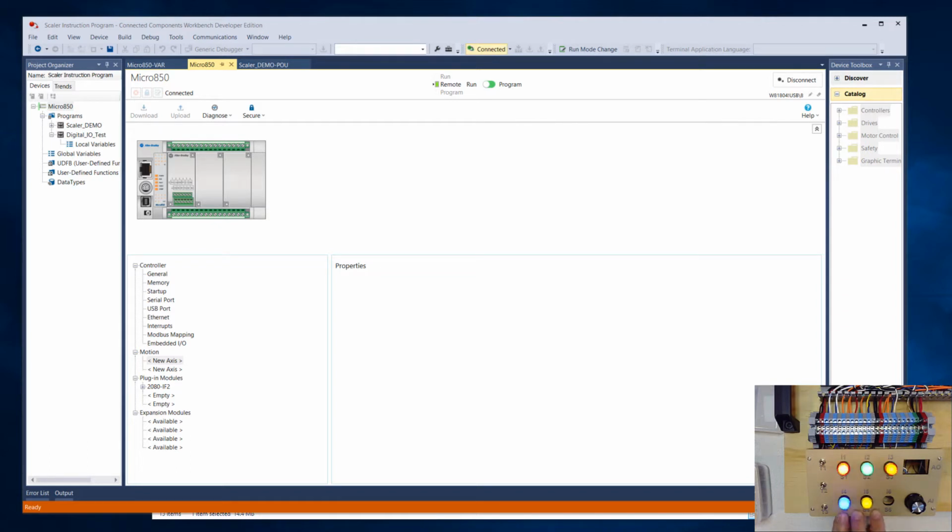So you can see it's flashing all of my lamps based on T3. Same thing we've done before, motor on T2. What we're going to talk about now is how can we use that analog input, that by rotating the potentiometer, we're varying a signal nominally 0 to 10 volts. And from our previous video, you saw that the actual input value ended up ranging from 0 to somewhere a little over 60,000. So that's great. We now have a way to have a variable number based on a physical change out here.